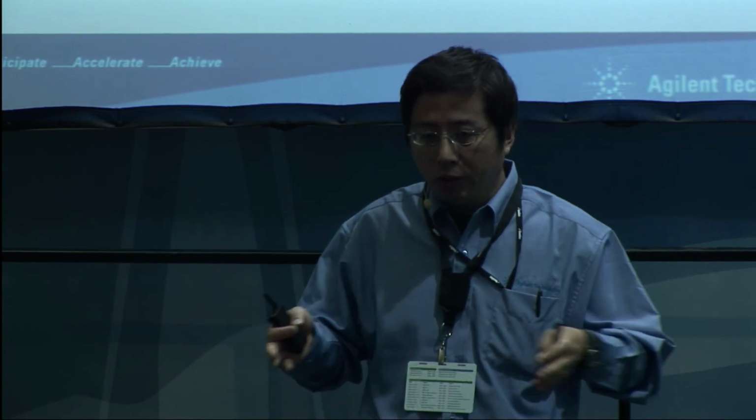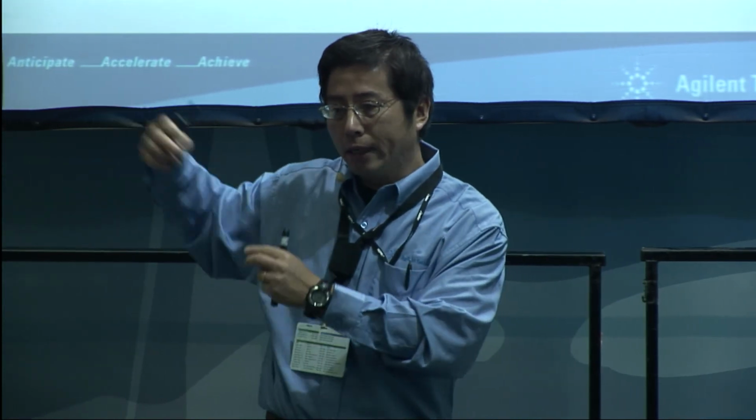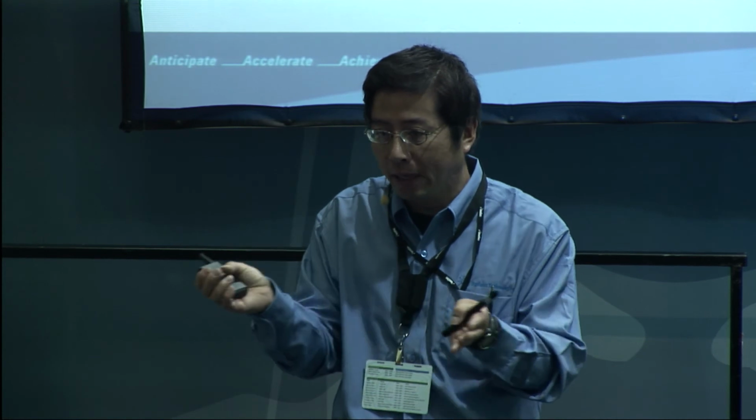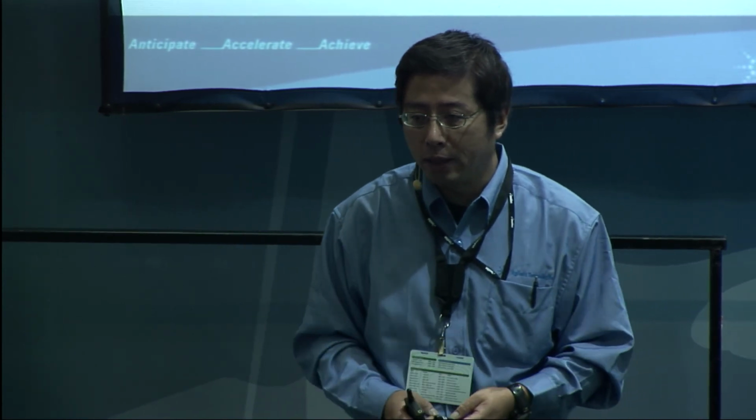If you have a small bandwidth, but you have a huge cable, and the connector you try to identify is pretty far away, then a very small bandwidth is fine. But if you do a fixture type of measurement, where each connector is only a few millimeters, then you need a very, very high frequency bandwidth. You have to play with that.